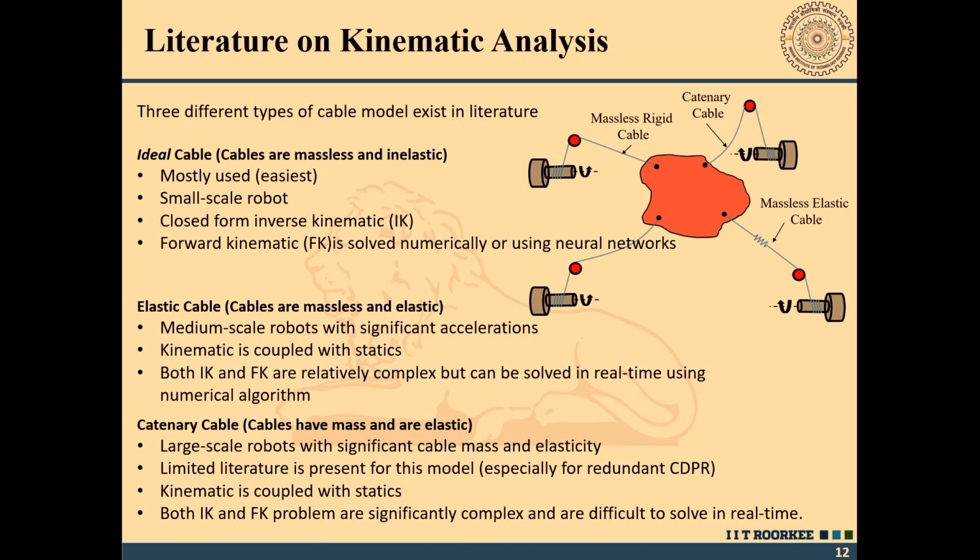And for the catenary one, as I said, these are used for the large scale robot with significant cable mass and elasticity. Limited literature is present in this case. Kinematics is coupled with statics, and both inverse kinematic and forward kinematic problems are significantly complex and are difficult to solve in real time.